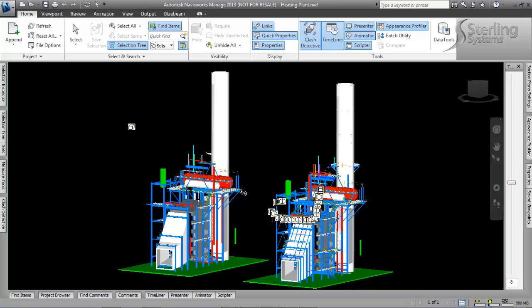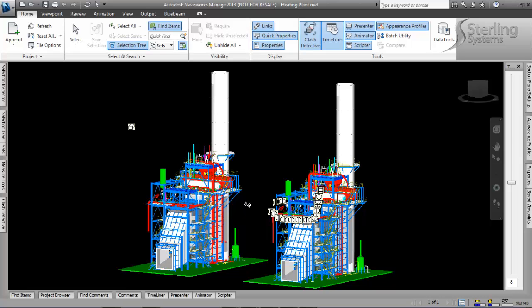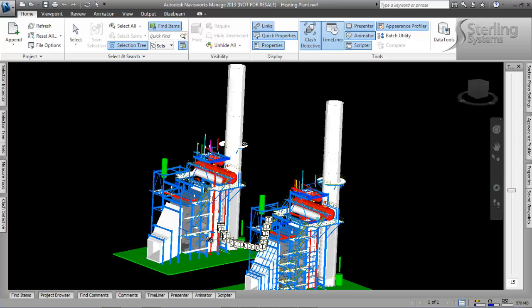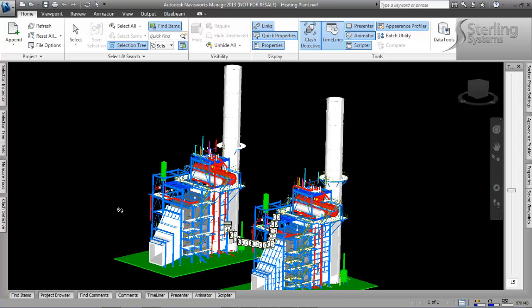If you've noticed, I've opened up several different types of files: an NWF file, an NWD file. An NWD file is basically a picture of the file. It's going to attach every file that it needs, hence the reason why your Freedom viewers can view the files. They won't be able to get in directly to each file or even have that file. Your NWF file is just a holder, using AutoCAD as an example, like your XREFs. So right now, all of our drawings in here are external. They're not into the Navisworks file format yet.